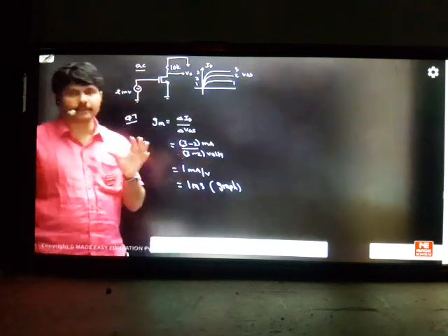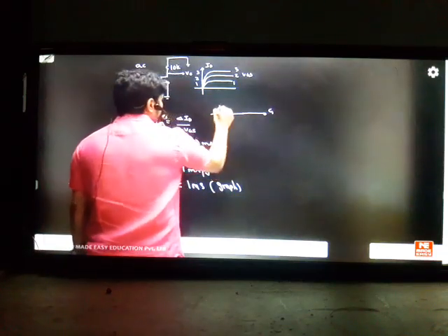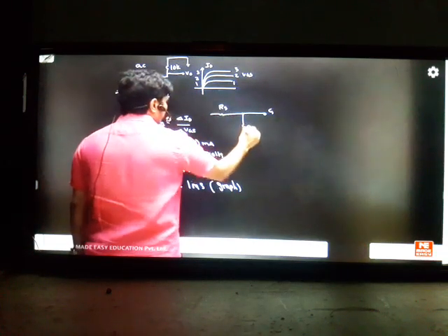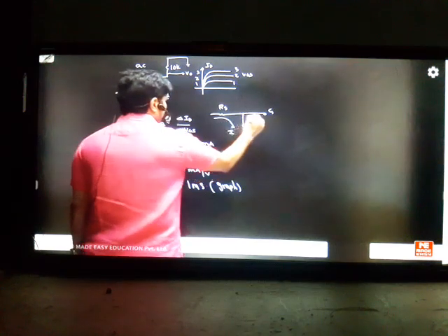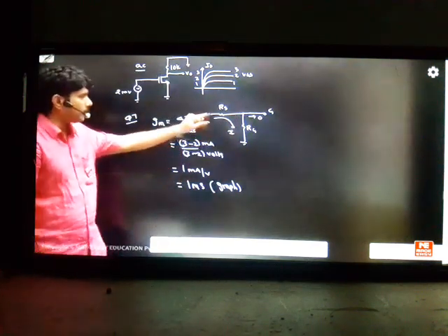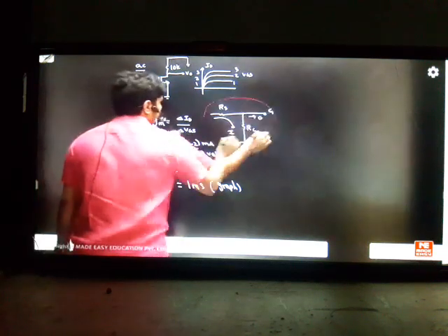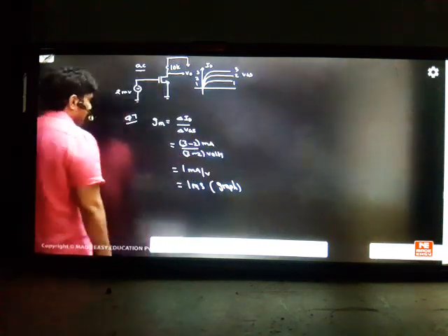Here we don't have a problem, but maybe the gate is open, as you said. If you have RS like this, but also some RT resistance here, then the impact will be there because the current can go this side. The current will be 0 toward the gate, but the current can go to the RT resistance. Definitely the formula will be valid here also. That's called voltage gain analysis.